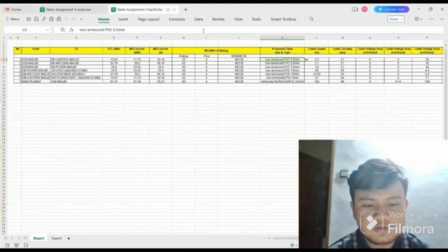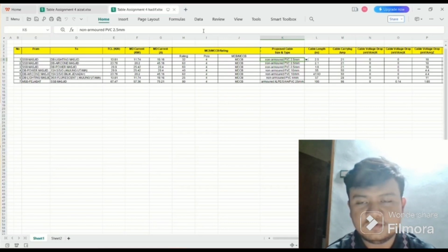Based on the requirement of MS IEC 60364-5-52, the voltage drop between the origin of consumer's installation and the equipment shall not be greater than 4% of the nominal voltage. This requirement is there to ensure that the voltage applied to the electrical appliance in the final circuit is maintained within proper limits. In the absence of other consideration, it is recommended that in practice, the voltage drop between the origin of consumer's installation and the equipment shall not be greater than 4% of the nominal voltage of the installation.